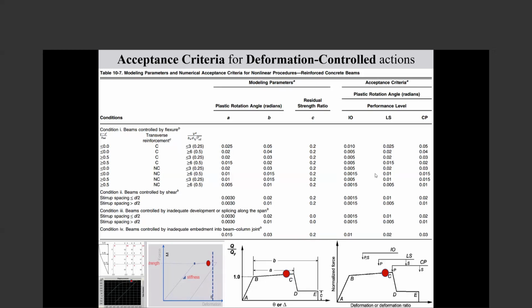Based on the curvature and the distance of each of these materials to the neutral line, it finds the strain in the material, then from the stress-strain curve, the stress, and then by the area of that section, stress to force, and then multiplying force by the distance gives the moment.